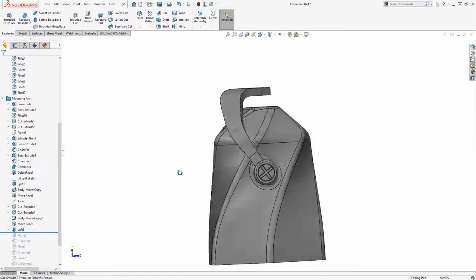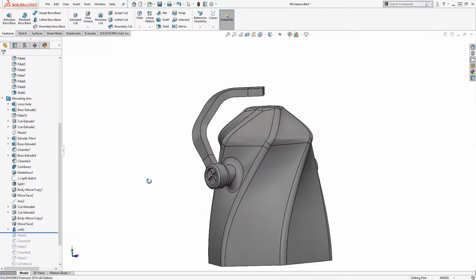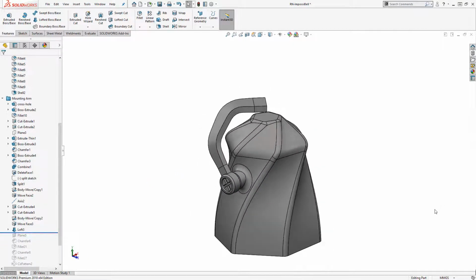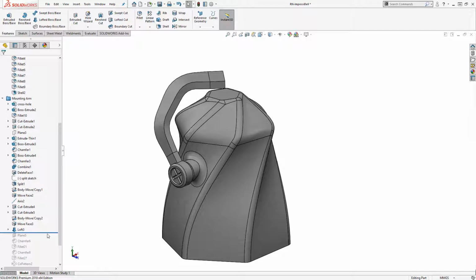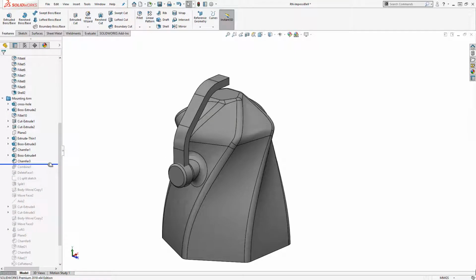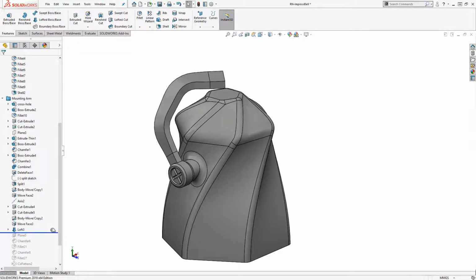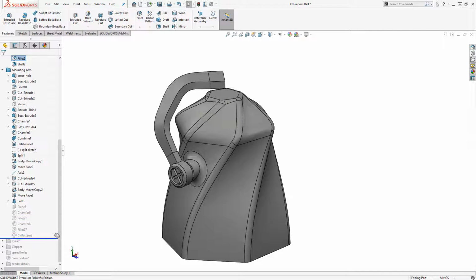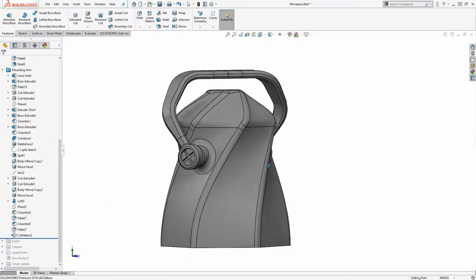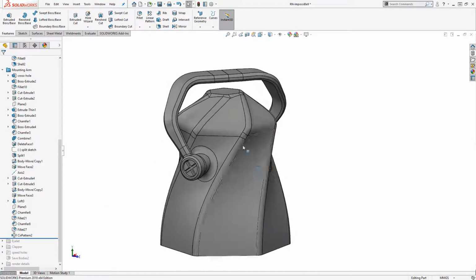So now I've created an arm that's twisted at the angles I specified, while preserving my design history, and it's kind of preserving my thought process here, because you can roll back and see, oh, okay, they started off with a straight arm, they got it functional, and then they realized that wasn't really the aesthetic they were after, so they went back in and lofted it. So ultimately, I ended up flipping this around at some point to match the twist of the bell ornament.